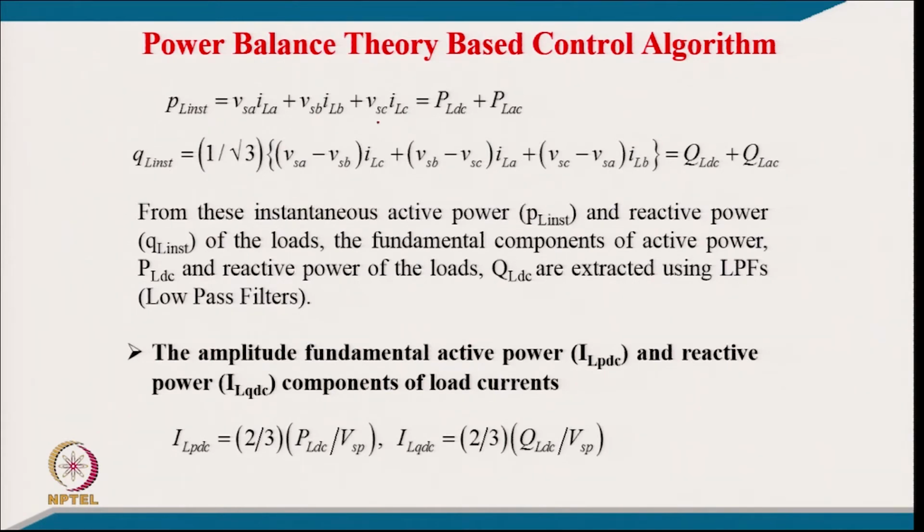So, we calculate the instantaneous power from these expressions: VSA ILA plus VSB ISB plus VSC ISC. So, it has a DC component and an AC component.